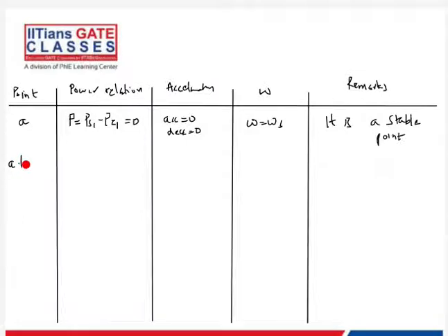Suddenly the mechanical input changes, so it has to transition from A to B. What is P right now? The mechanical input has already reached PS2, but the electrical output is still PE1. So this would be positive, and this will cause acceleration. And omega would be greater than omega s. So what will happen? Delta will increase. Is this clear?